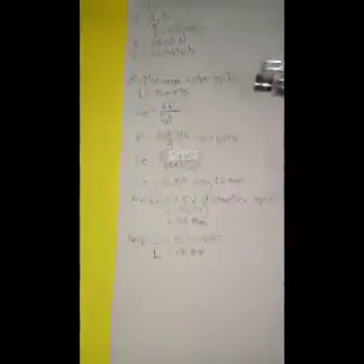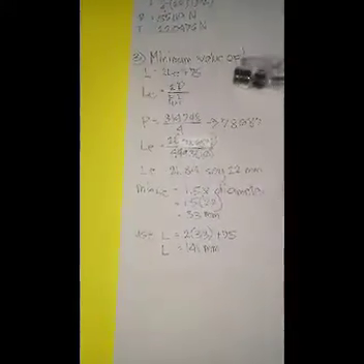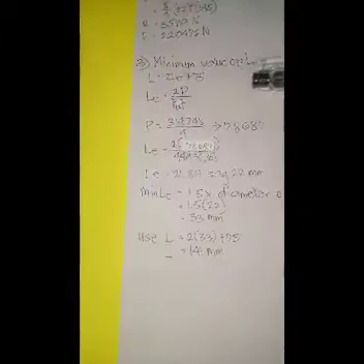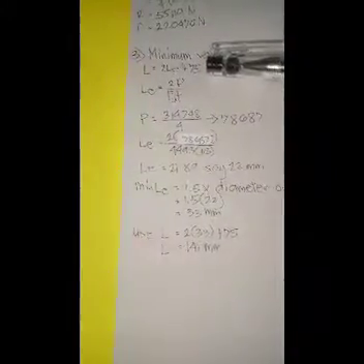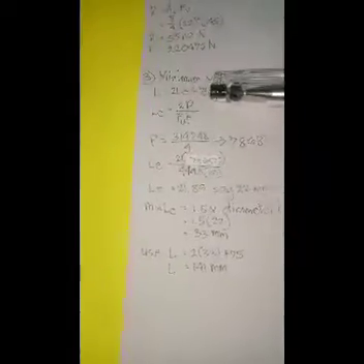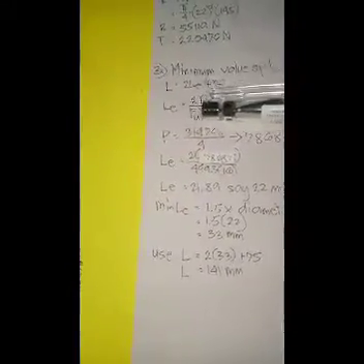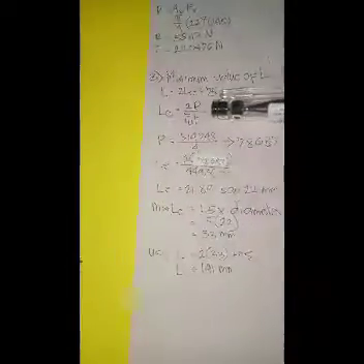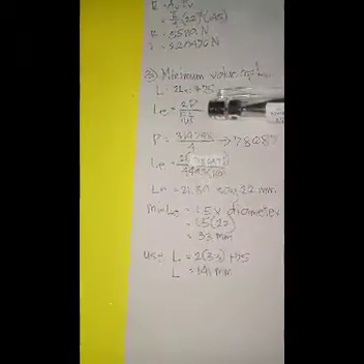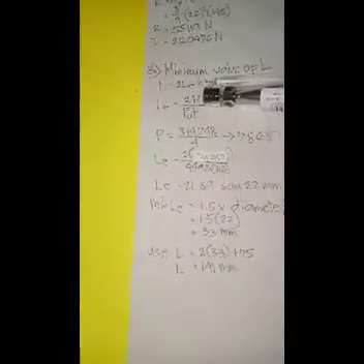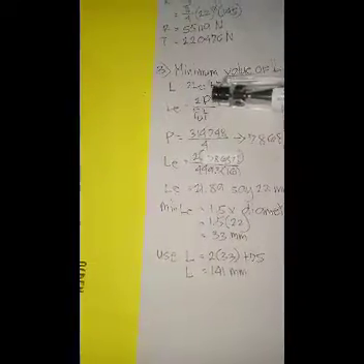Then the minimum value of length. Number 3. Our length is equal to 2 times L sub e plus 75. The 75 comes from the diagram in figure 3.11. We don't know the value of L sub e, so we use its formula, 2 times V over F sub u times t. Then we need to find V, since we don't have this value.